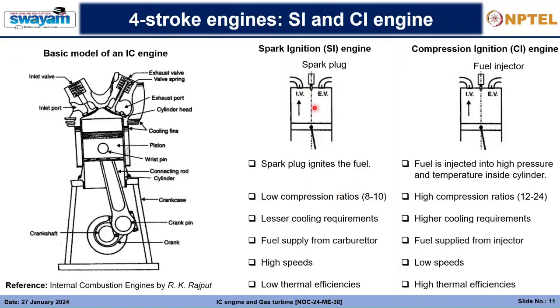It is quite less in this because we are using external means to ignite. But here, how much it should compress the mixture should be quite high, to create this high pressure and temperature in order to have the combustion taking place. Because the compression ratio is quite low, lesser cooling is needed here. But here higher cooling is needed because the pressure and temperature are quite high, and you need to cool this system and avoid the burning and melting of this cylinder.